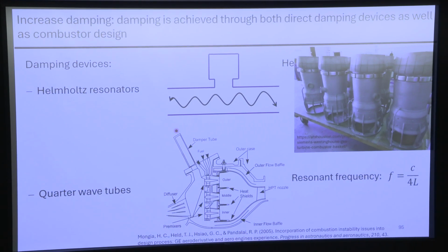The resonant modes of particularly gas turbine combustors change. If you install a power generation engine in the summer, the installation team will come back in the winter and retune the engine because just being cold outside changes the frequencies of the engine. And then they'll probably come back next summer because enough will have changed. So you have to tune this thing kind of continuously. And one of the things they're doing when they're tuning it is changing the settings of those quarter wave dampers to suppress any instabilities in operating modes that you want to run at. So these are 2 different passive ways of dealing with it.